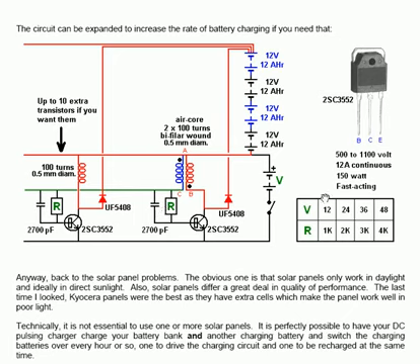That means that the power rating of that resistor is going to be something like 12 volts at 12 milliamps, which is 144 milliwatts. That means that a 250 milliwatt resistor, which is a typical ordinary quarter watt resistor, would do perfectly well for that particular resistor there.